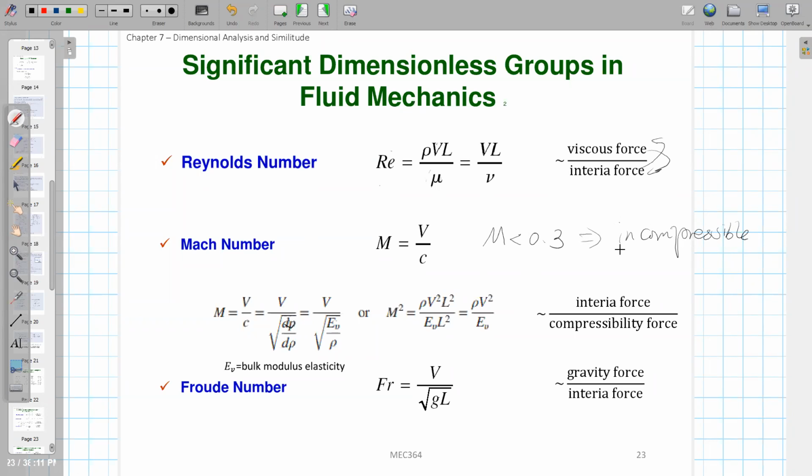And that is why you will see those behaviors, like anytime you see shock waves, Mach disks, those kinds of things. You see those flow structures because they have a very sharp change of the density in a small region. That's the reason you see the shock wave. The flow density across the shock wave will change greatly. So that's why you only see those aerodynamic behaviors for compressible flow, because Mach number is large, flow will become compressible, density will be changed.